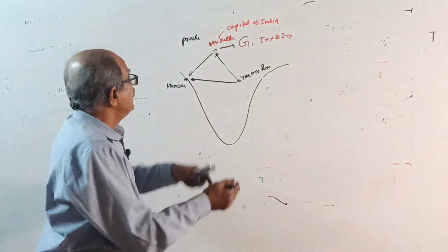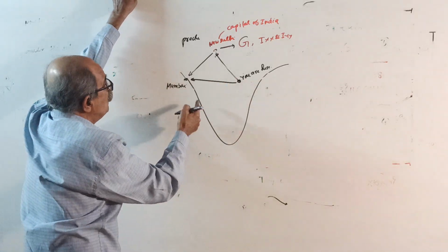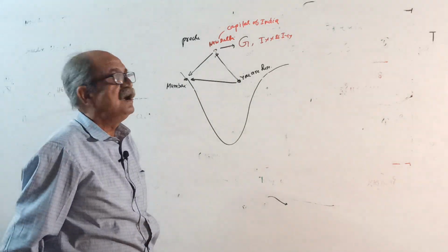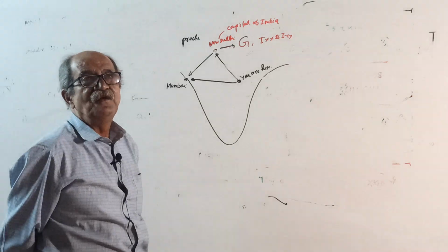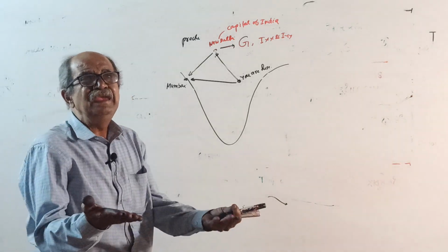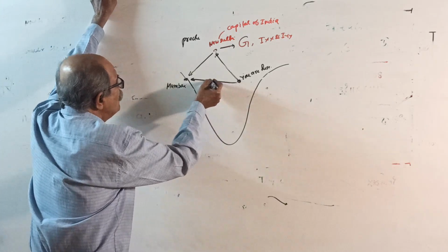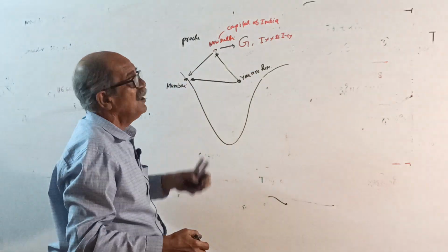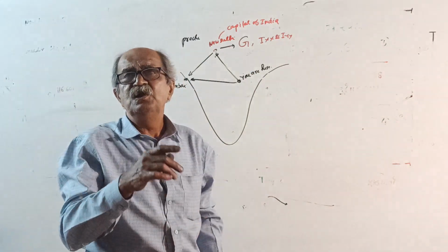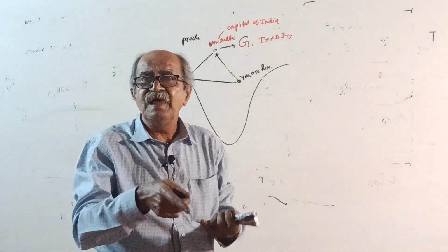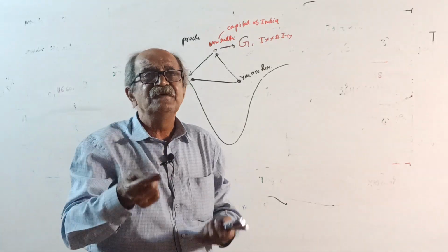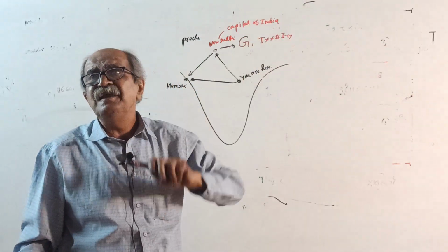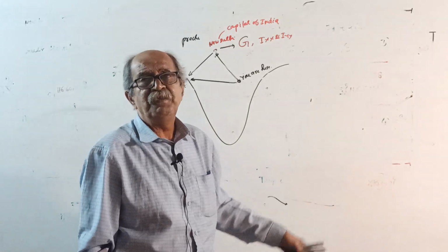But suppose you are here. Someone tells you, go to Mumbai. Then if you ask which is the capital of India, New Delhi, and say, okay, I will first go to New Delhi and from there to Mumbai, they will tell you, why? There is a direct flight from here to Mumbai. Go to Mumbai directly. Why do you want to go to the centroid? So, if they ask the moment of inertia about a centroidal axis and then some other axis, first find I about the centroidal axis. Using that, you find I about the required axis using the parallel axis theorem.